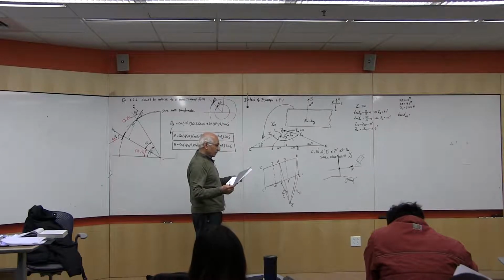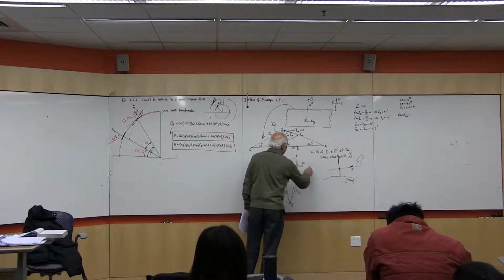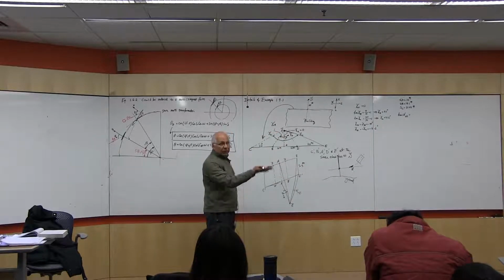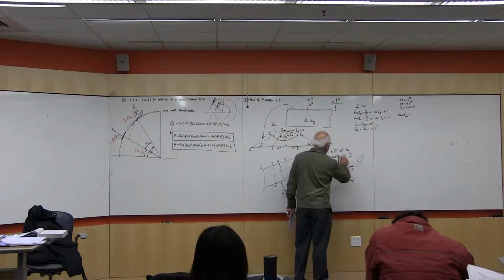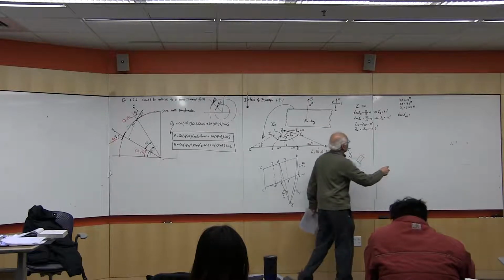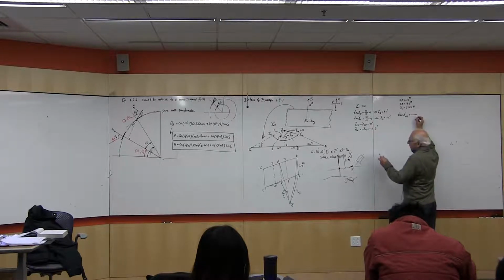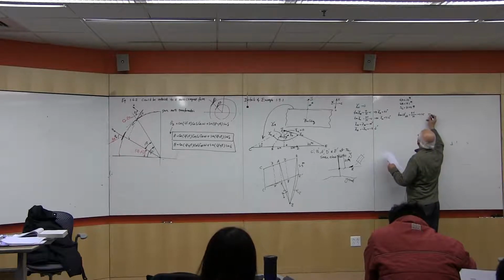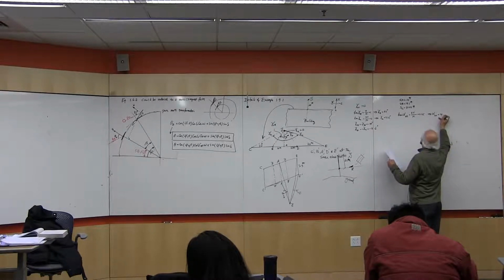Two and a half meters. That's the height of the building above the location of the solar collector. So in a way, this is 2.5 meters, a one-story building. So tan of alpha OA, therefore, is 2.5 over 10, which is 0.25. Out of that, I get alpha OA to be 14 degrees.